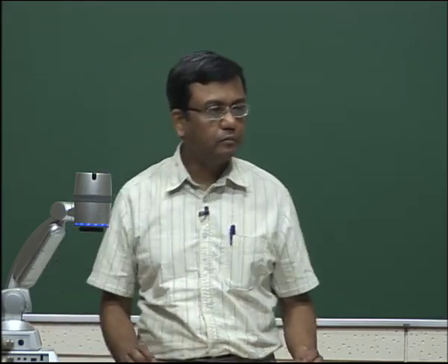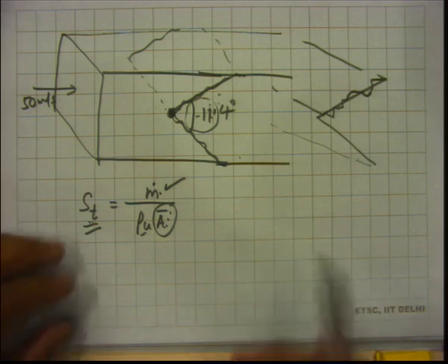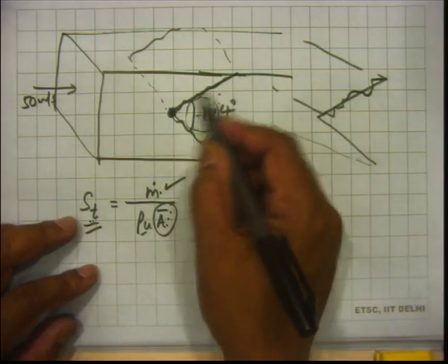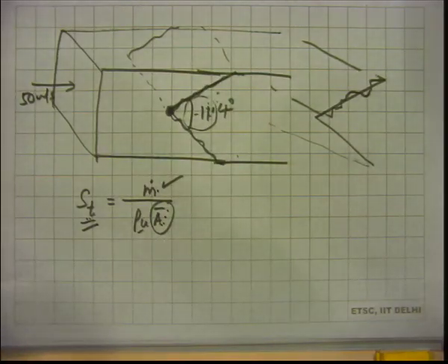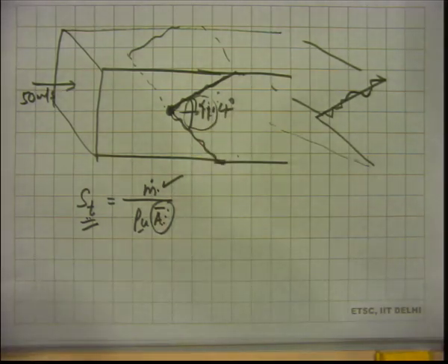Yeah. This problem, that A bar should be taken normal to that velocity, right? So it should be A bar sin theta. A bar is the area through which this ST is getting burned, no? So A bar will have to be the full area. So it's not like laminar burning velocity, that it should be normal to stuff like that. No, it's actually the flame area. Okay, so the flame area will mean this multiplied by this, the dimension perpendicular. Okay. And will you get an angle, half cone angle here, or half wedge angle here? If you do that, will you get the half that angle also?